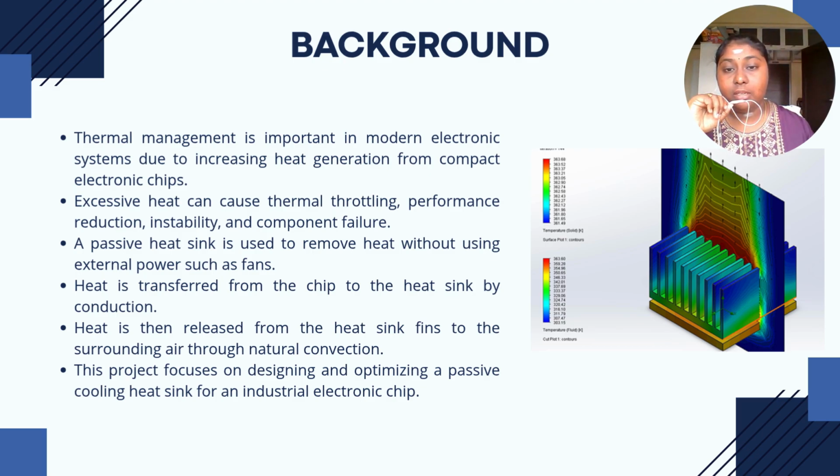A passive heat sink does not require external power such as a fan to operate. Instead, heat is transferred from the electronic chip to the heat sink through conduction. After that, the heat is released from the fins of the heatsink to the surrounding air through natural convection. This project focuses on designing and optimizing a passive cooling heatsink for an industrial electronic chip. The aim is to improve heat dissipation while keeping the design simple, reliable, and suitable for natural convection cooling.